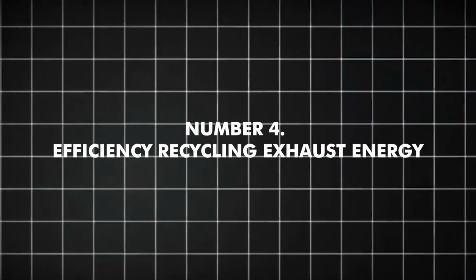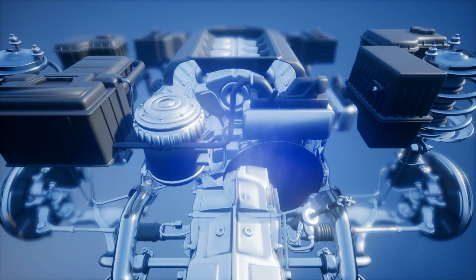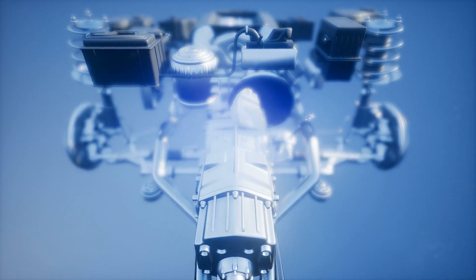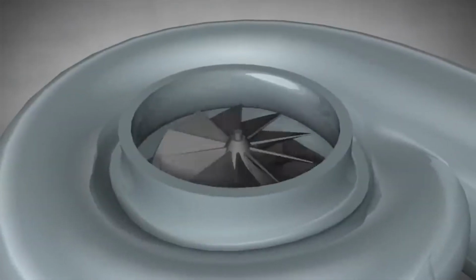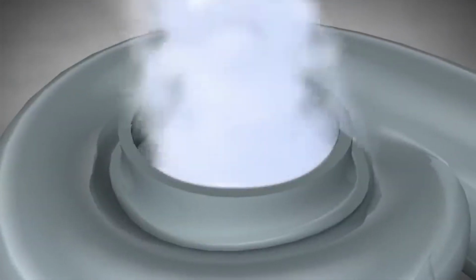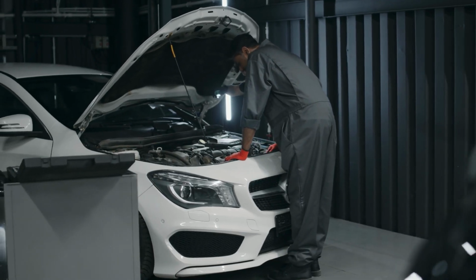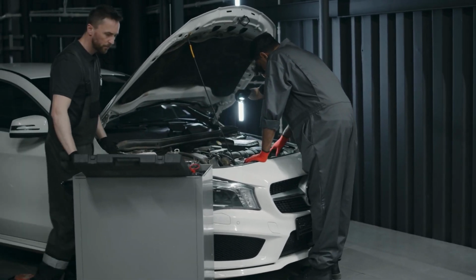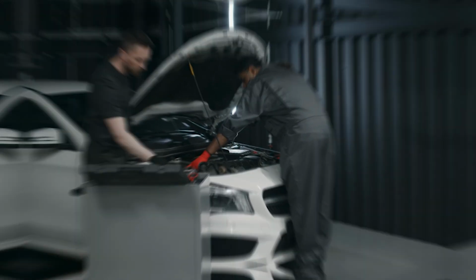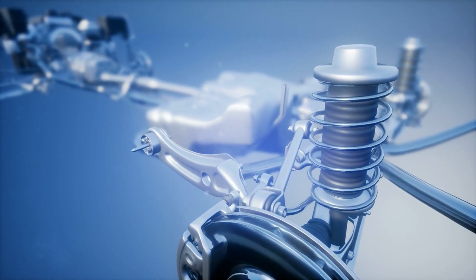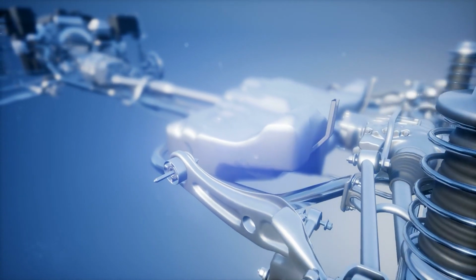Number 4. Efficiency: recycling exhaust energy. One of the fundamental efficiency advantages of turbocharging lies in its use of exhaust gas energy, which is normally wasted in non-turbocharged engines. Unlike superchargers, which draw mechanical power directly from the engine's crankshaft and cause a parasitic power loss, sometimes up to 20% or more, turbochargers are driven solely by the energy in the exhaust gas flow.